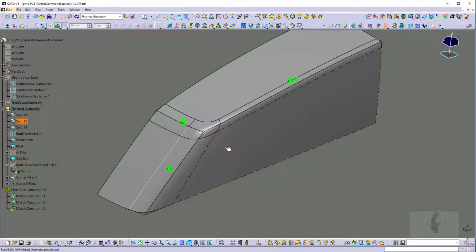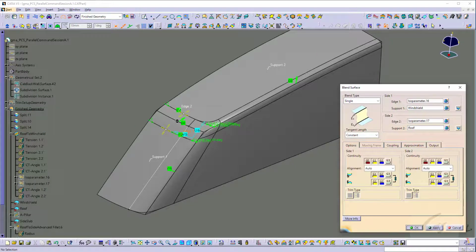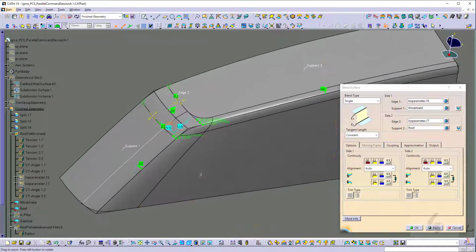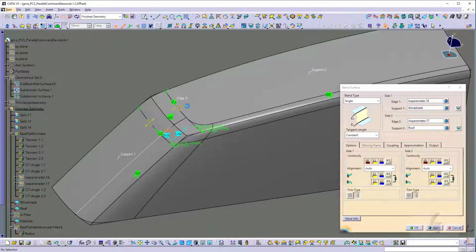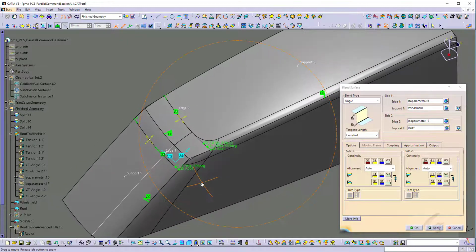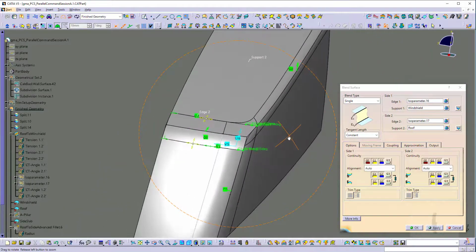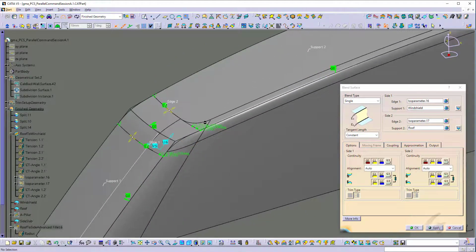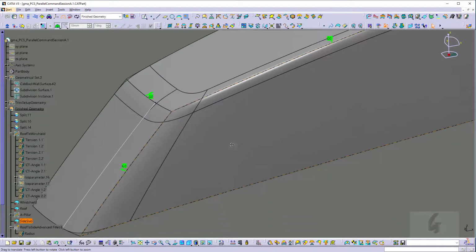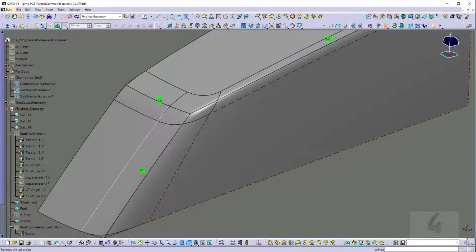If you're familiar with CATIA, then you already know the typical workflow. For example, in this part, I can easily make a change to a feature like this roof to windshield blend. So I am going to pull on the roof limitation boundary, stretching it rearward. And you may notice that the corner blend to its right also updates. This is the standard power of CATIA feature-based design. Okay, I'm just going to undo that modification to revert back to the original state.